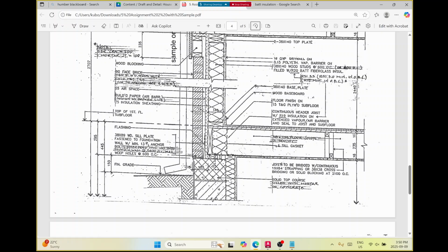We're going to stick a special bolt in here that's going to be sunk in the mortar but stick out a little bit. And that's going to become the anchor point for a piece of wood called the sill plate, and then the rim joist, and so on. And from there we transition to wood construction. So that's what we're going to focus on next class.